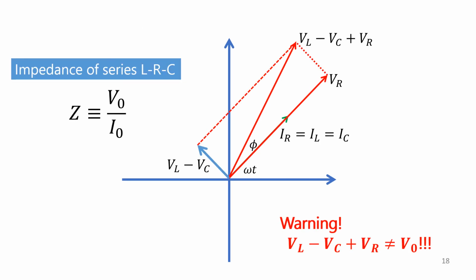Recall that our goal is to look for some formula for the impedance Z. This should be easy enough because remember that the lengths of the phasors, V and I, are the magnitudes of the quantities that we want. From our modified Ohm's law, we have Z equals V naught over I naught. I naught, or our maximum current, is usually given with the current function. It's usually what's beside the cosine. V naught is the voltage source magnitude.